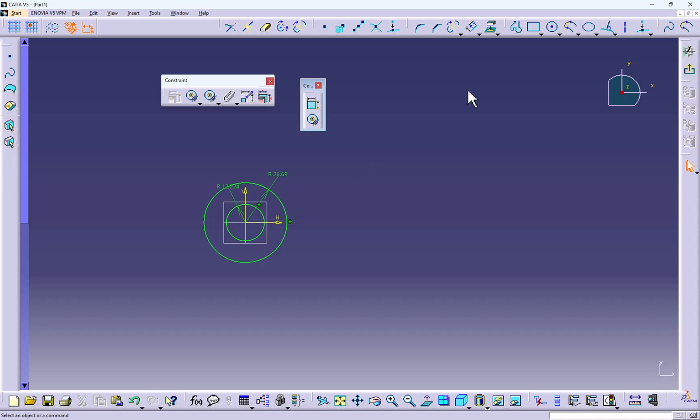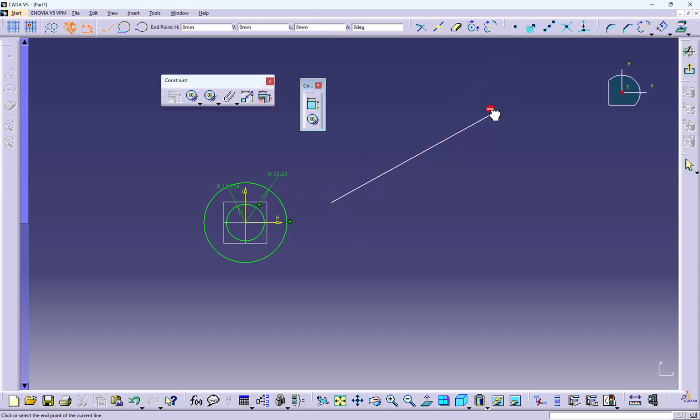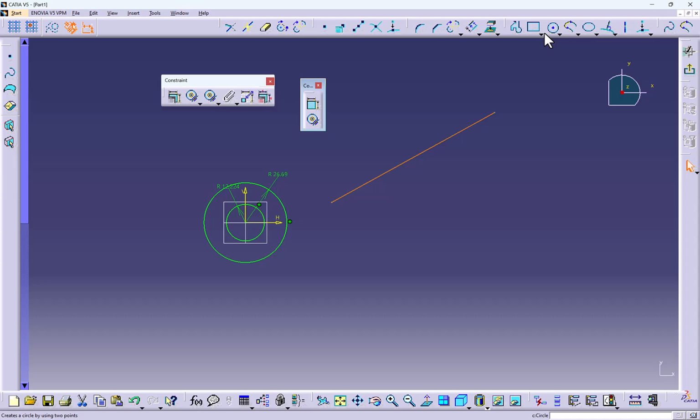This option can work in one more way. If I have a line and an arc or circle, and you want to make it tangent with that line, you can do that. Let me add some size to this and this. So I'll go to this option and select this line and this circle. We can see that it becomes tangent here. So this way, this option can be used as a contact and a tangent method.